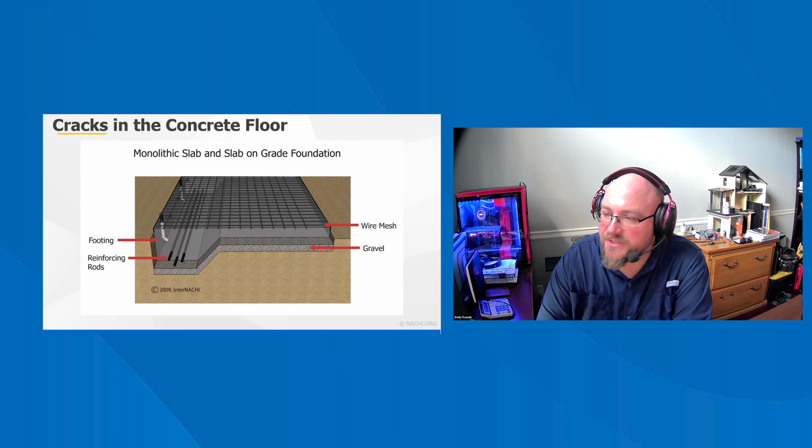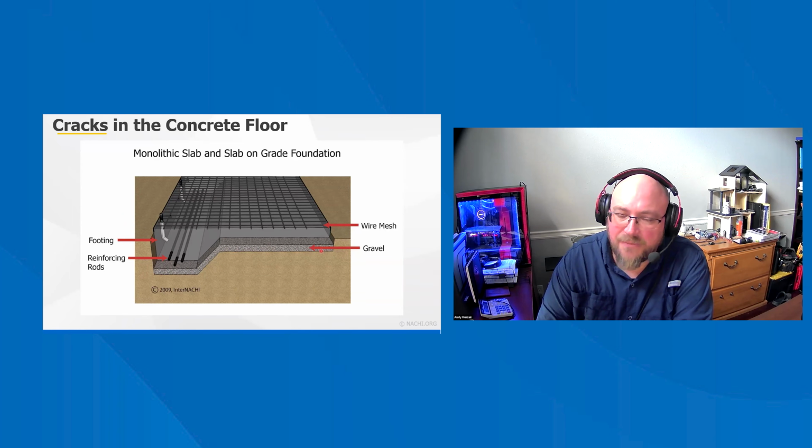Concrete and masonry stem walls may be reinforced with horizontal reinforcement bars in a manner similar to that recommended for basement walls. For difficult site soil conditions, expansive soils, or weak soils, other types of concrete slab foundations may be more appropriate, such as mat foundations and post-tension slabs.